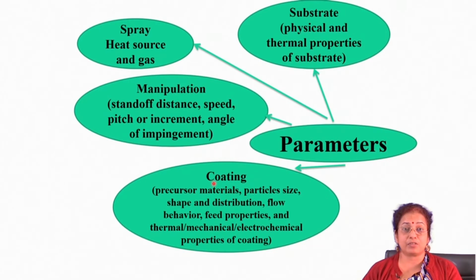If you are interested to develop very thin, nanostructured coating, then you have to look for either HVOF or maybe kinetic spraying as the coating technique.